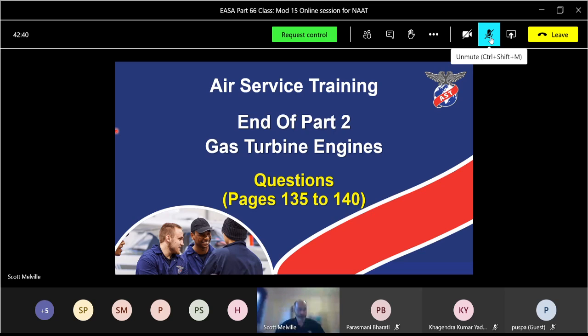From what sources does the low pressure air starter get its air? So we can get air from various places for the air starter. Where does it get its air from? From the APU. No, it's big enough from atmosphere. Yeah, APU, a little jet engine. Ground supply and engine, from the engine which is already running.